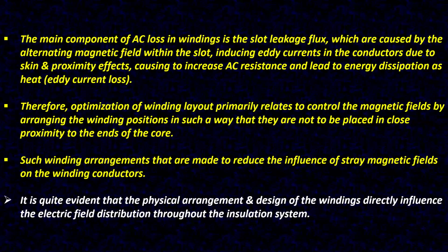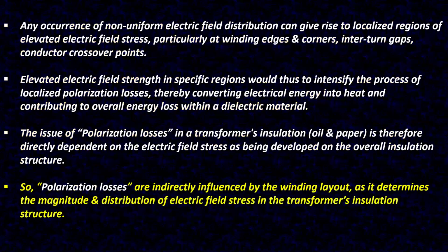Most important, any non-uniform electric field distribution can give rise to localized regions of elevated electric field stress, particularly at winding edges and corners, interturn gaps, and conductor crossover points.